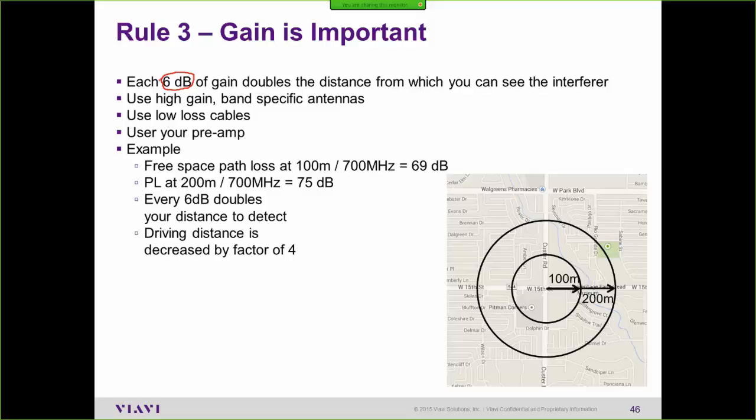So do everything you can to get good gain and low DANL. That means low loss cables. Make sure your cables are good. Turn the preamp on inside the analyzer. All those things are critically important. Again, here's another slide on DANL, but I think you guys have gotten the message. Here again is the same kind of setup keys to set up that spectrogram sample I showed you. All right, and then finally, path loss estimates.